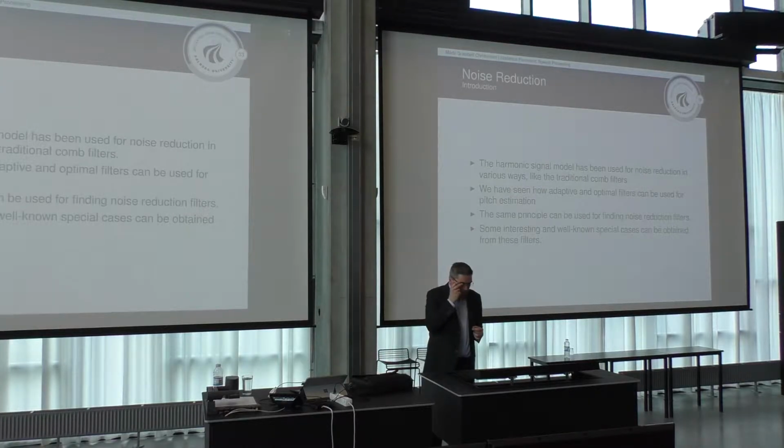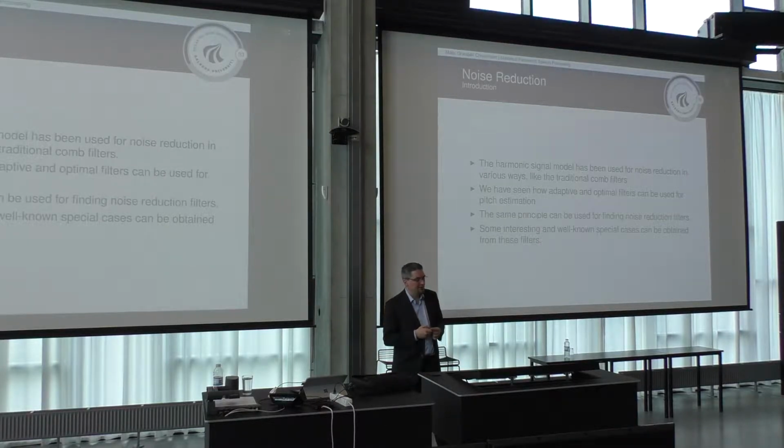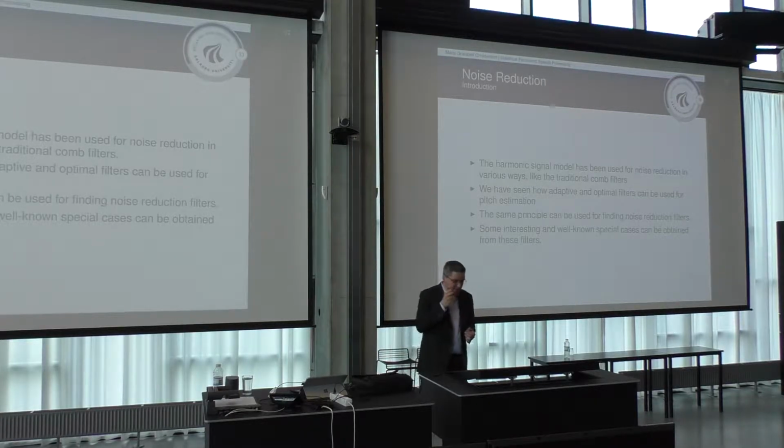Let's look at noise reduction. So the harmonic signal model has been used in many different ways for noise reduction. Many of you probably know about the traditional comb filter, which has been around for many, many years. But we've seen now that we can actually design adaptive and optimal comb-like filters that can be used for pitch estimation. And that principle can also be used for noise reduction. And as you'll see, we get something interesting out of that. And it also reduces to some really interesting special cases.